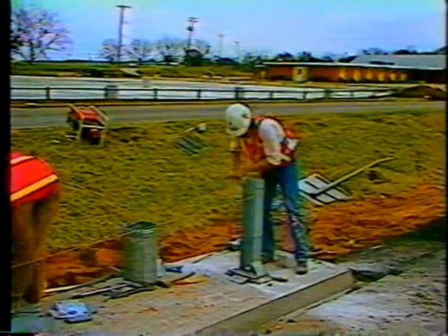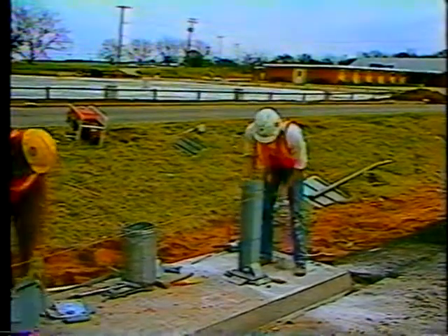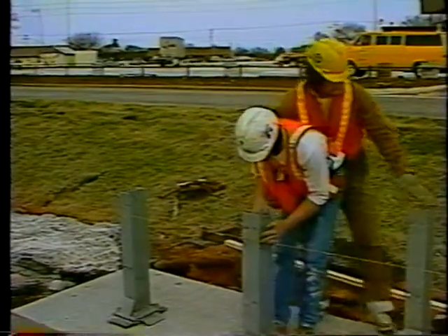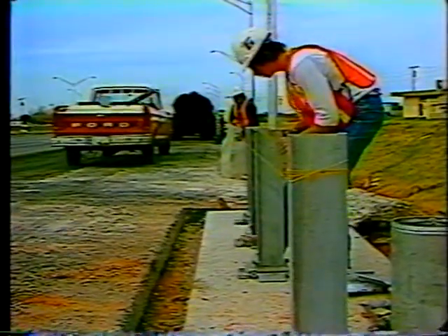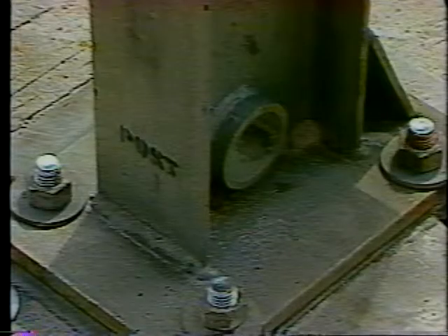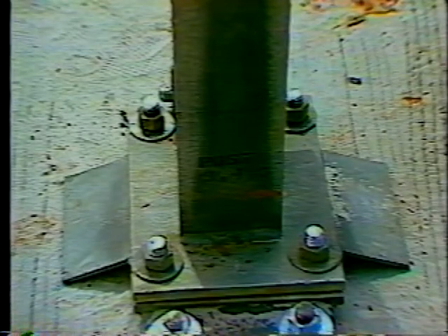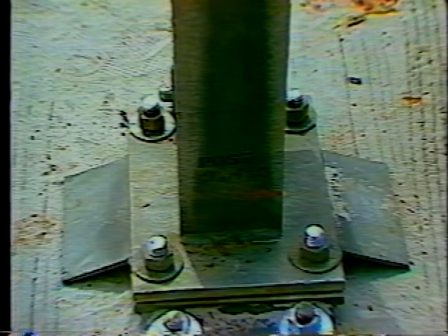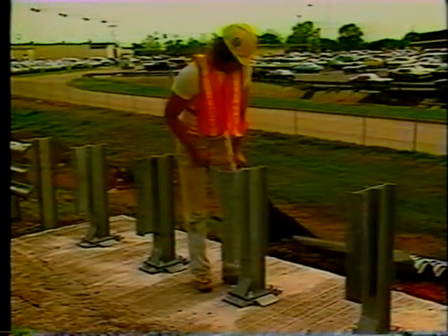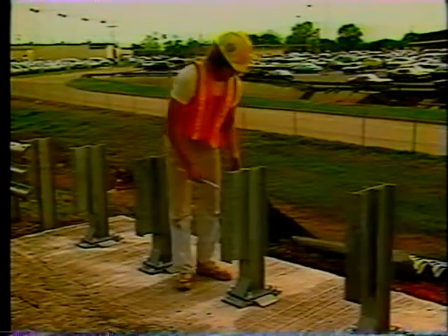Careful alignment of the slip bases is extremely important. They must be aligned to each other as well as to the finished grade of the road. Check alignment parallel to the roadway once all 5 bases are in place. Posts 1 and 2 are similar except for the cable hole in post 1. Posts 3, 4, and 5 are different from posts 1 and 2 and must be positioned accordingly. Next, attach a blockout with the 2 hex head bolts and nuts called for and tighten firmly.